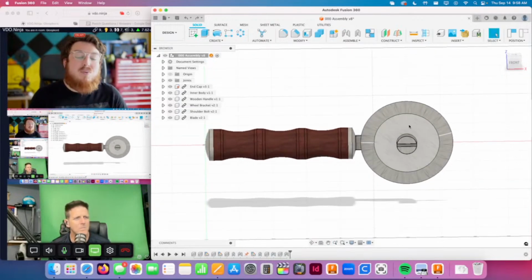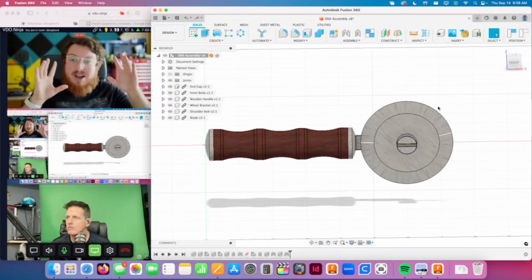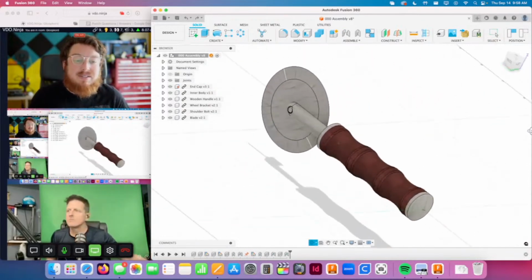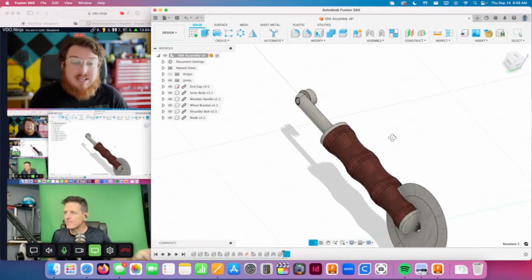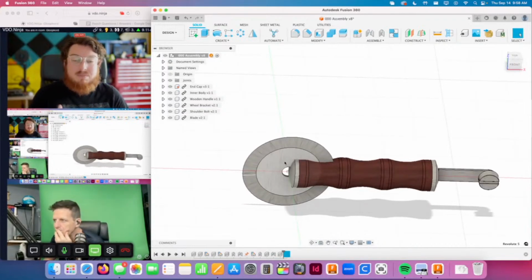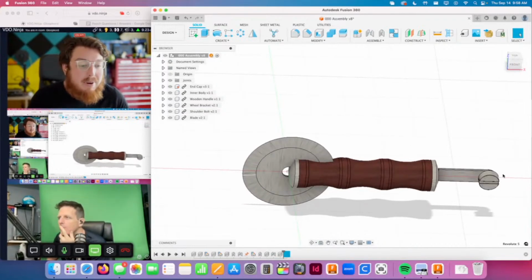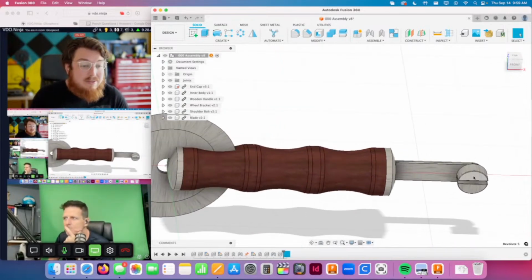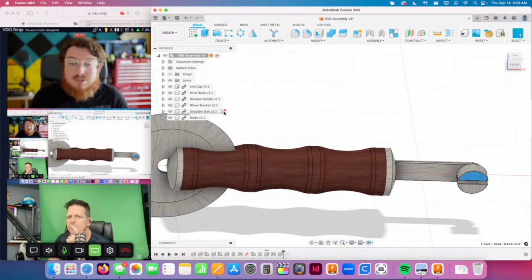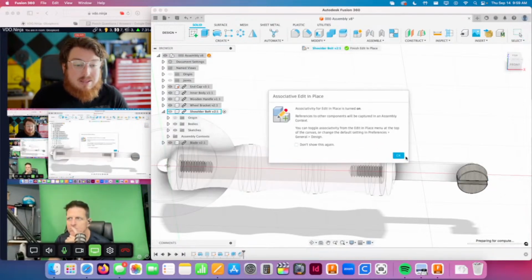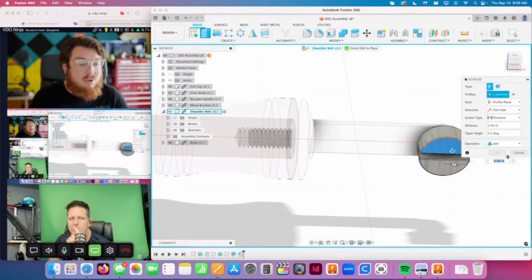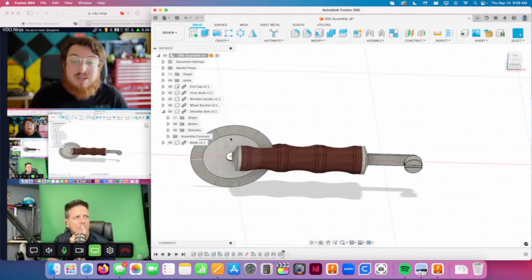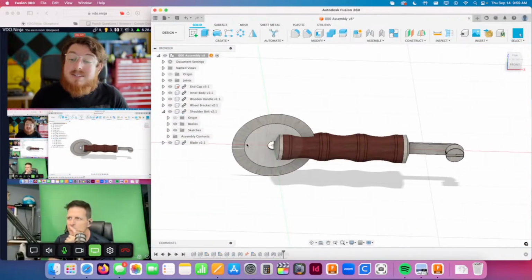Okay, so if I'm building, and let's say this is what the end product is going to look like. Let's say I haven't put on this last joint. So this is where it was made in the Fusion universe. But I want to edit something about this. If I try and edit this piece right now, it's going to say, yeah, that's fine. And I can change something about it. I can extrude that face if I want, for example. And that's fine because nothing about this component is affected by that component.